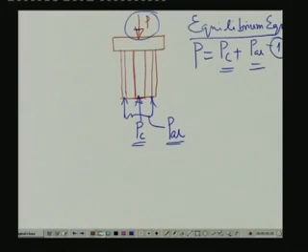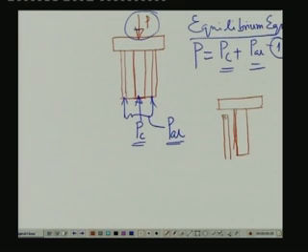So, now let us look into what is going to be the compatibility equation in this particular case. Let me look into another free body diagram of the top part of the system. This is the bearing plate along with the copper rod, and the sleeve is in this location, and this is the gap, since the copper rod is 0.05 millimeter greater than the sleeve. This is an exaggerated form, and let us say after deformation the bearing comes in this particular position. Hence, the deformation that the copper rod undergoes is this much.